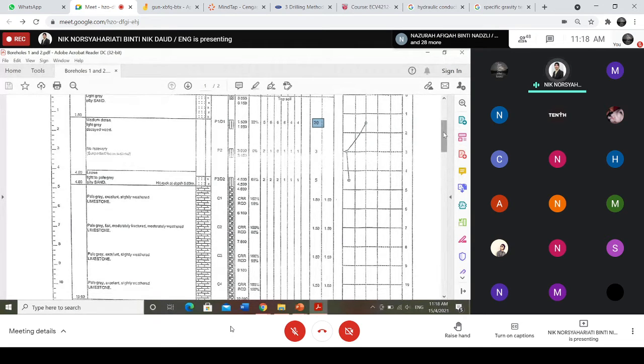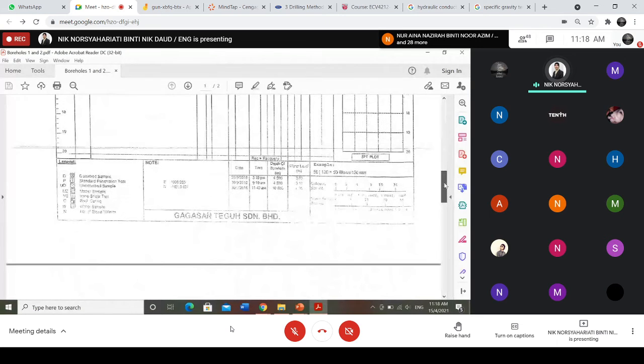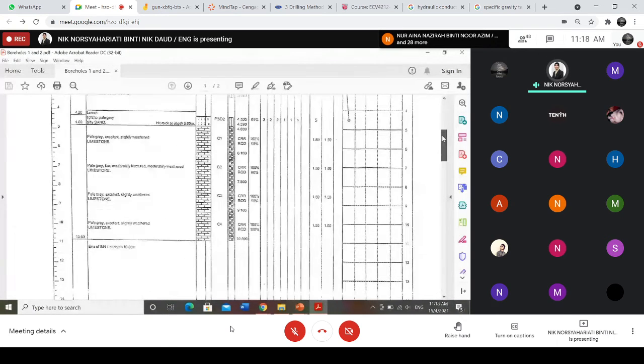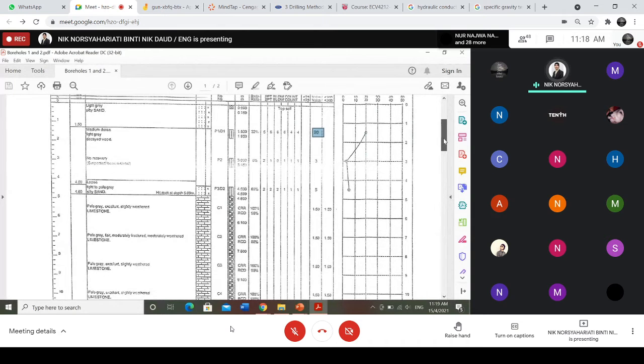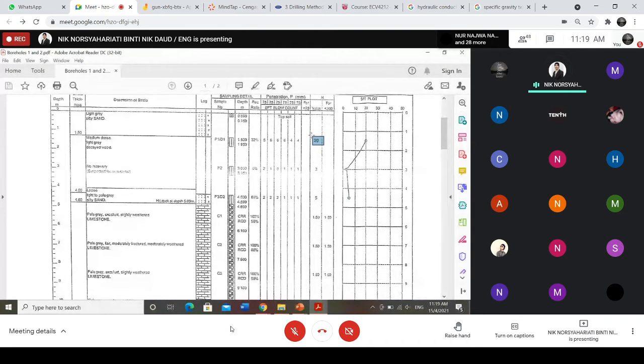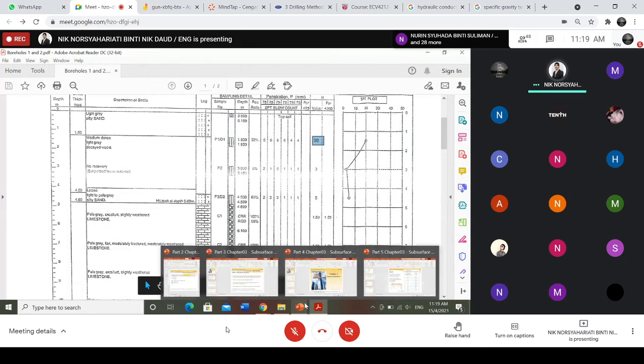All right. For this one, I don't want to talk more about it, but of course you need to go through it. You can just go to Google and find any site investigation borehole logs and have a look. There will be different presentations, but at the end of it, you need to get the N value here. This is important because you want to find out the bearing capacity of your soil. After that, you can proceed with the calculation and design of your foundation, right?